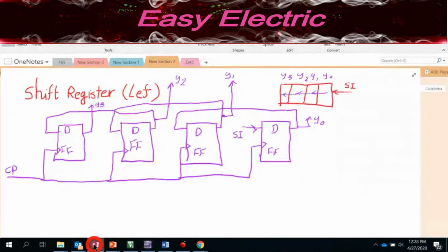So let's go back to the design. That is the clear and set button that we have on the flip-flop, right? Remember we talked about some pins, which is the clear, CL bar, and we have another pin on any flip-flop, which is preset, PRS bar. So whenever you activate these two, the bubble of this circle that you see will be active with 0.